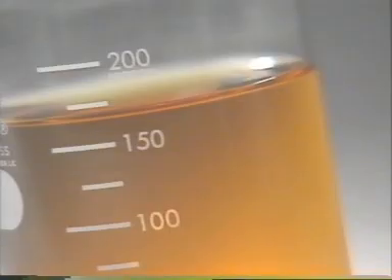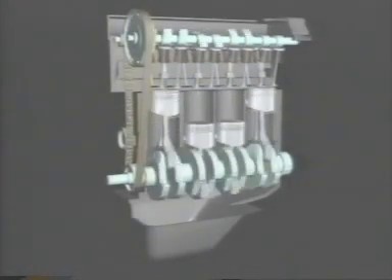The lubrication system supplies engine oil to each part of the engine so as to form an oil film on part surfaces, thereby minimizing friction and wear. Parts thus lubricated rotate or slide smoothly, enabling optimal engine performance. Four-stroke engines normally use a pressure-type lubrication system.